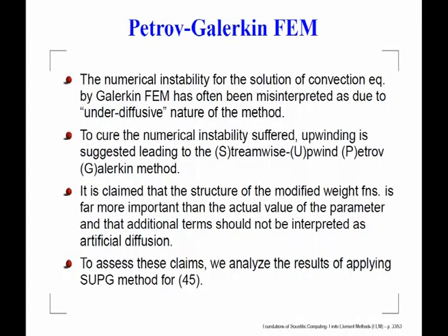The problem comes when you have coupled space-time dependence, and that is what prompted the early practitioners who wanted to use the finite element method in fluid dynamics scenarios. They realized that you will have to develop a methodology which will work when you have simultaneous space and time dependence, and this is where they gave up on the Bubnov-Galerkin approach.